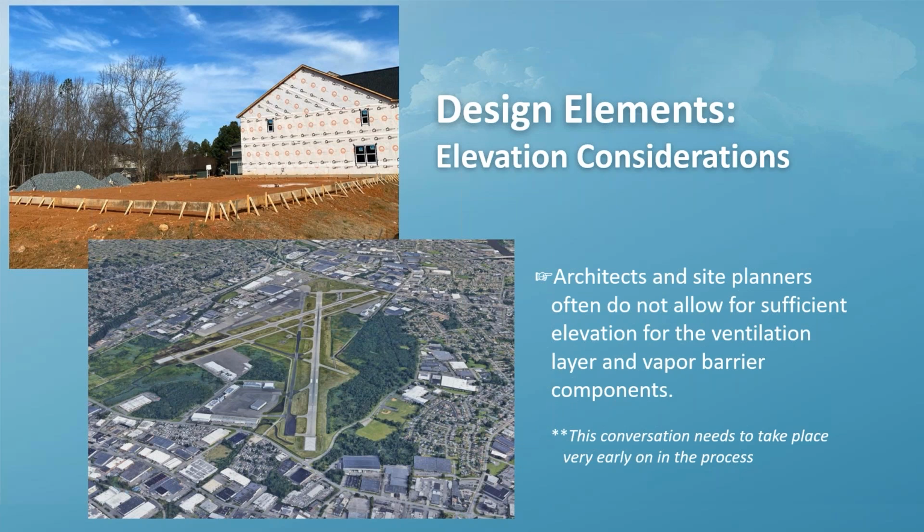So if we have between 8 to 11 inches of stone and 3 to 4 inches of DGA, and you're talking about a 400,000 square foot big box building, that's a critical elevation, or even a 200,000 square foot building, because we couldn't take any soil off site. So if you start building up the elevation of the inside area, then all of a sudden out in the parking lot, you have a problem with drainage, runaway shopping carts, and all these things because of slopes. And all this needs to be figured out and conveyed and the site adjusted. This all happens at the front end with the architect.